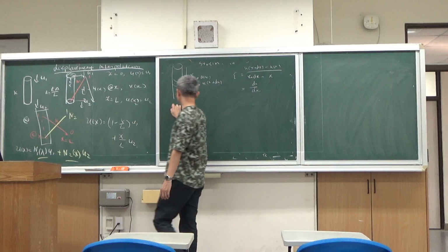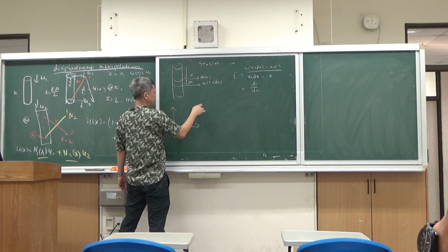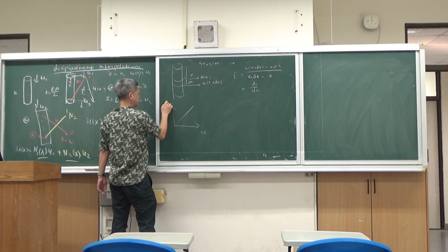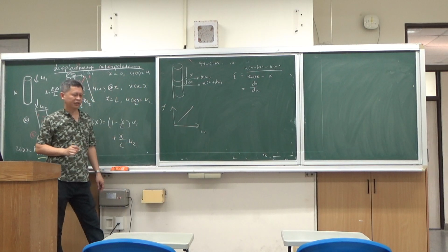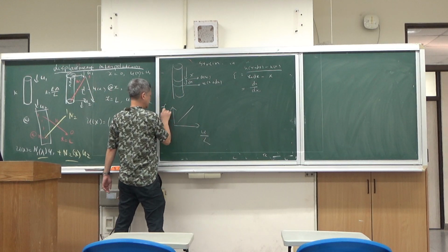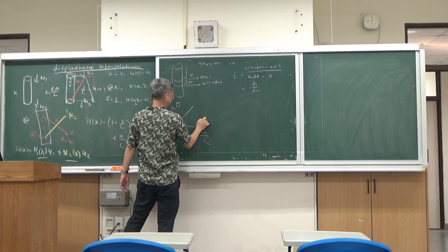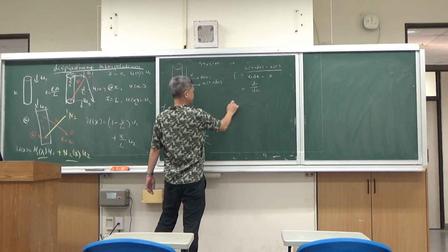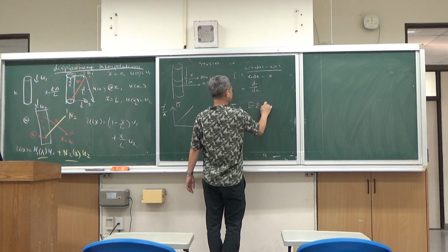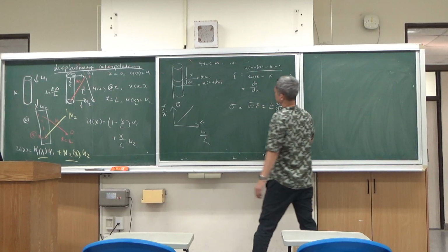And then recalling your Hooke's law, you might previously have force versus displacement. And if you now divide by the length, divide by the area, then you're going to have the stress and the strain. So now the stress is equal to Young's modulus times the strain, E du/dx.